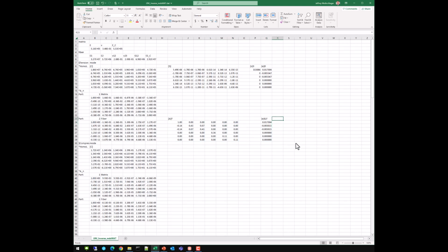Okay, I need to calculate the stress of the fiber. And the stress of the fiber is just going to be equal to the E of the fiber times my strain. Stress equals E times strain. And so I get 565 KSI, give or take, which is exactly the number I'm going to put into my form. And then I want to figure out what is my strain in the fiber with zero stress. So that's just 1.1 times the strain in the fiber at initial failure. So that's 1.9%, give or take.